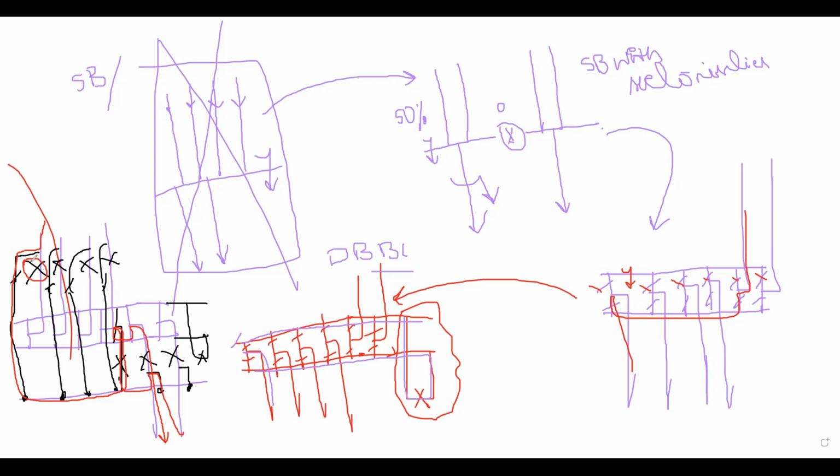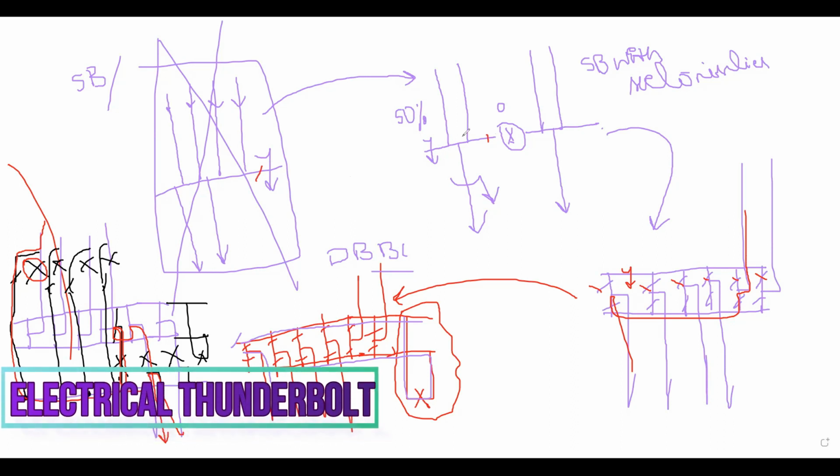So that's the reason in every case you can see only two buses. But with two buses, why so many schemes? Because they are not worried about the bus there. They are worried about the breakers. So from here up to the double busbar, it is fine.